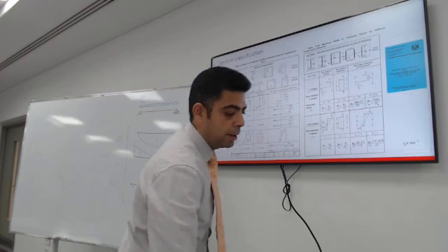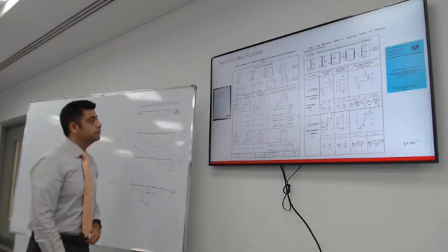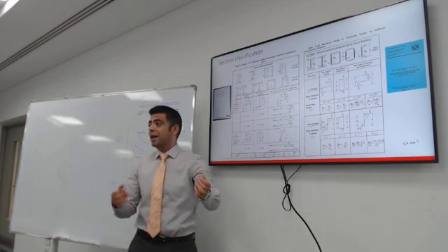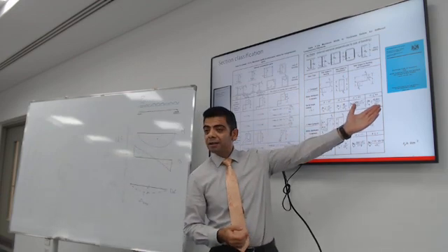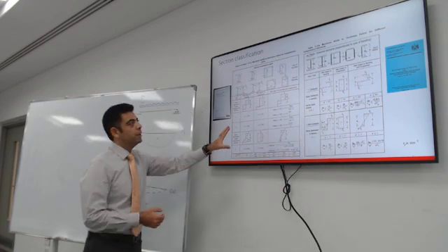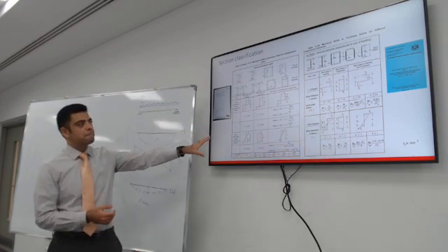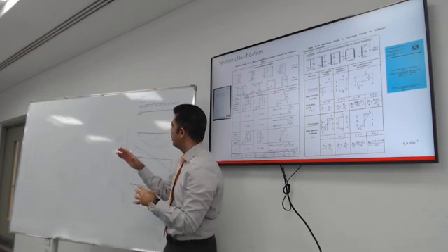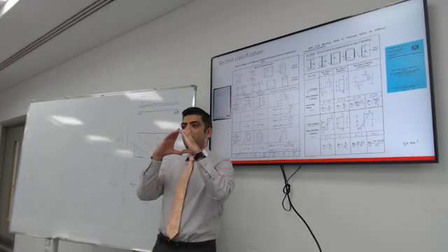All right, how does that work? You reference the correct standard. The Egyptian standard has these figures, tables. The European standard has these figures. And what it says is, look at the section you want to use. Let's say we want to use an I section or a box.